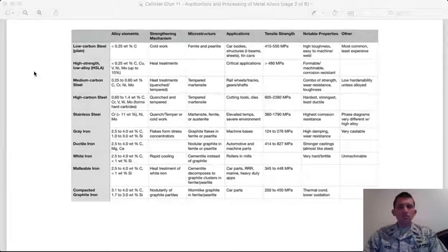We'll talk about the Jominy end quench test, where you physically can't get the heat out of these parts fast enough to form bainite or martensite much more than right at the edge. And so you don't strengthen low carbon steel through heat treatments, you do it through cold work. You can still deform them and create those dislocations, but the microstructure is going to be pearlite, because without other alloying elements, the microstructure can develop very rapidly.